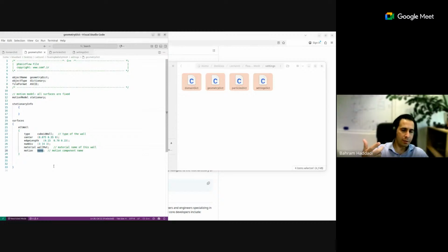That's one option. The other option, which I find very nice, is that you can import it from an STL. If you have an STL file, you can import the geometry from an STL into your simulation, which is quite useful if you have a very complicated or rather complicated case. For example, you might already remember we have this screw conveyor. That's a quite complicated geometry that you cannot generate that easily with such simple functionalities. Therefore, you simply make an STL file, a surface file, in a CAD program like FreeCAD, CATIA, Salome, or whatever, and then just import it in here.